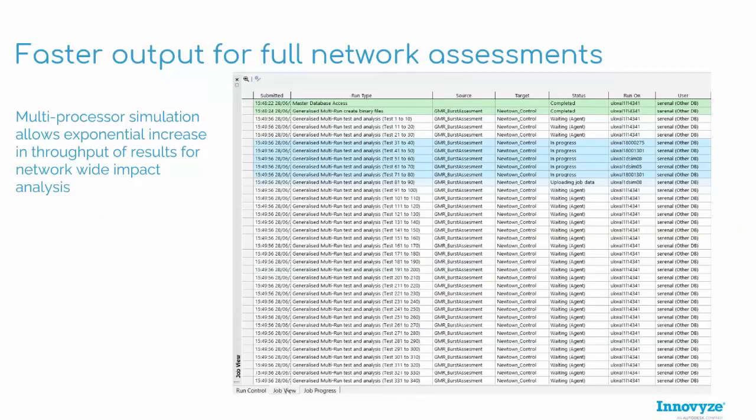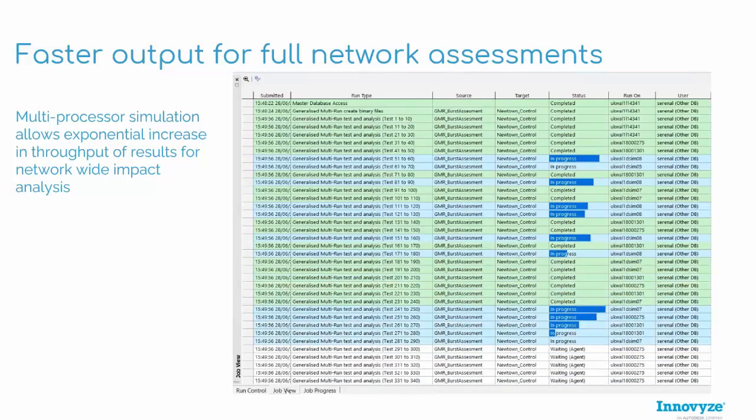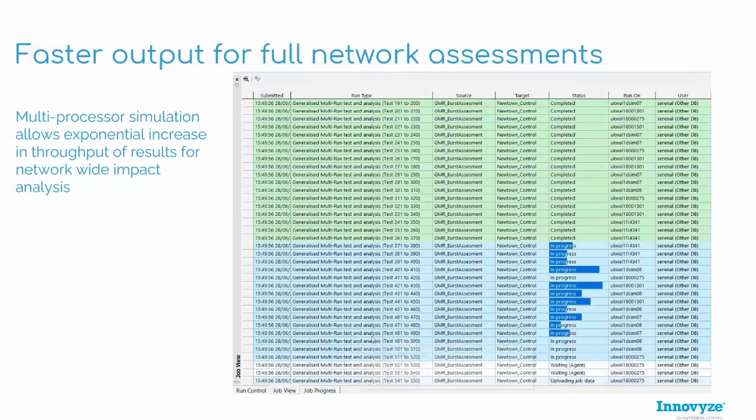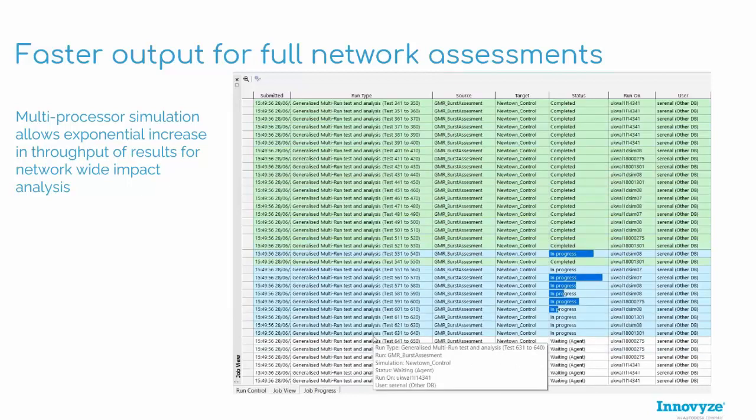And how we can do this. So all of the things that we've looked at for resilience can be done on a full network. So we're not just having to choose specific pipes or specific hydrants we want to do fire flow tests on. You can select your whole network with no need to make it smaller or remove pipes or skeletonize it. You could select the whole network or all of your assets and run this analysis. So you're not missing anything. You're not missing any type of valve that could be important to the assessments that you're doing.